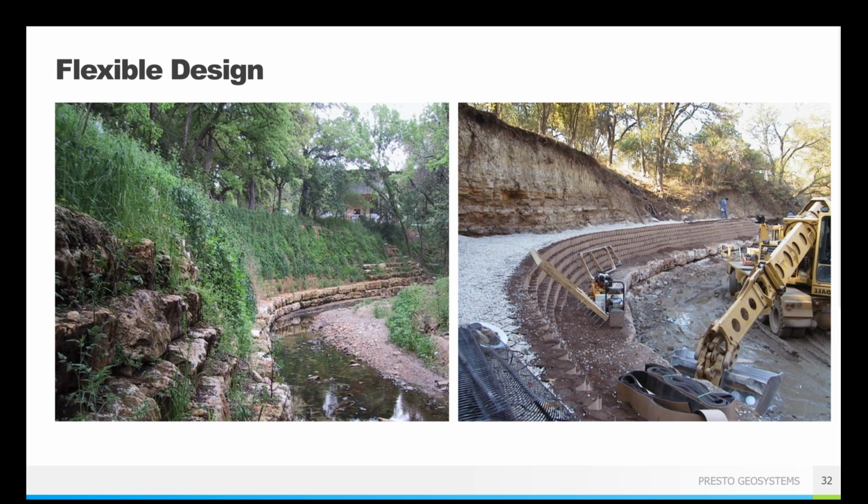And as anybody who does work with water on a regular basis can tell you, going around corners is where you have the highest potential for erosion in these types of applications, because you've got that turbulent flow, you're moving from one direction to another. Definitely an area of concern.